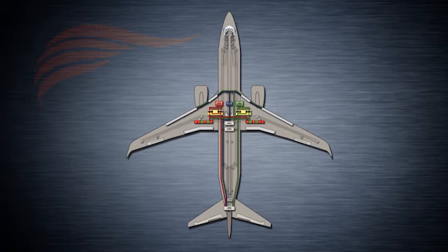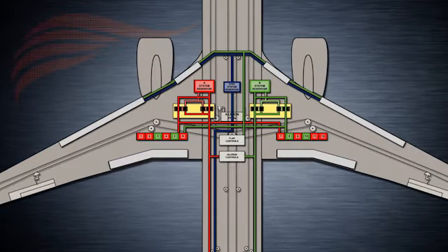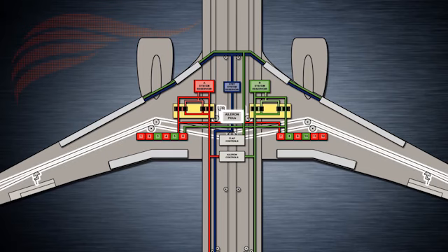The systems that run along the center line are connected to aileron body quadrants near the forward bulkhead of the main landing gear wheel well. Both body quadrants are connected to each aileron PCU. If one hydraulic system is off, the other PCU commands both quadrants. The body quadrants are connected to the wing quadrants through the wing cables. So when a wing cable moves, it moves the related wing quadrant and finally the respective aileron.